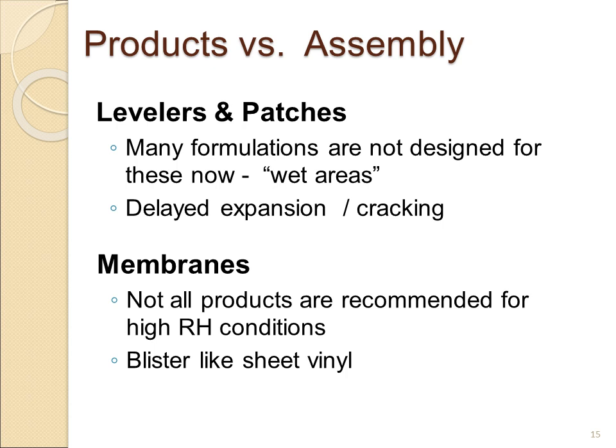And those conditions could be really damaging to the entire project, and they may not happen for months afterward, but it could be from excessive moisture. Same thing with membranes. Not all membranes are recommended for these types of applications. Some have a range, and we'll talk about ranges a little bit later as to where they're acceptable and where they're not. And if you've been installing over damp materials, you'll see that some of these membranes can blister up like sheet vinyl because of the moisture vapor that's in a mortar bed or moisture that's in a concrete slab.